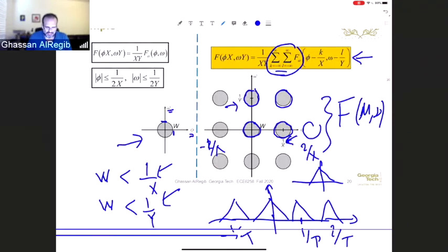In the 1D case, we have capital T controlling our sampling interval, or our periodicity in the frequency domain. And when you are sampling a spectrum, it can be a triangle just for illustration purposes. Then if the signal is band limited, with the maximum frequency in the signal less than 1 over T, then the fact that I'm sampling means that I am doing this repetition of my spectrum.